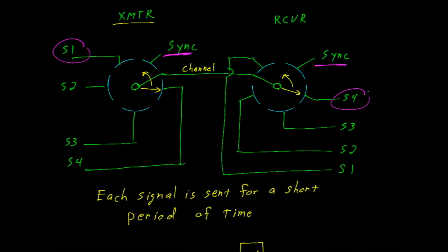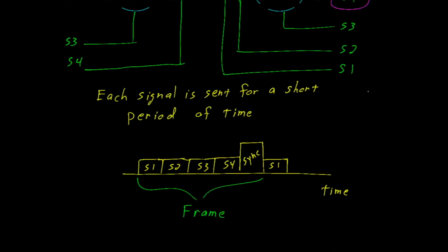Know that there are many different ways to solve this problem. One method, an analog method suggested here, is to send a sync pulse, which has a much higher amplitude than the other signals. That would allow it to be easily detected, and the receiver would automatically move to that zero position every time the sync pulse was received.